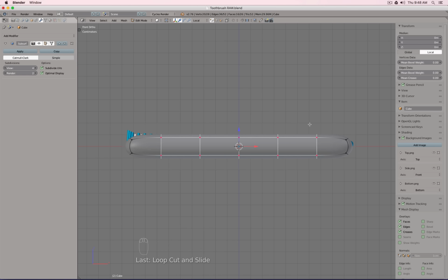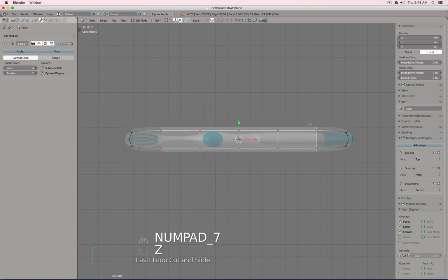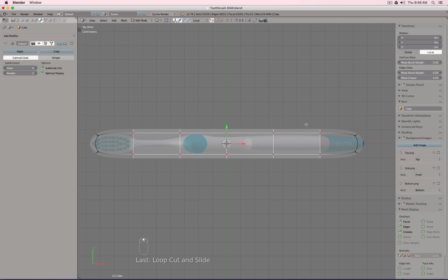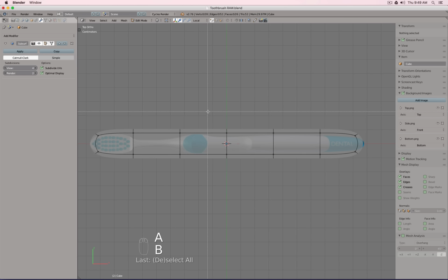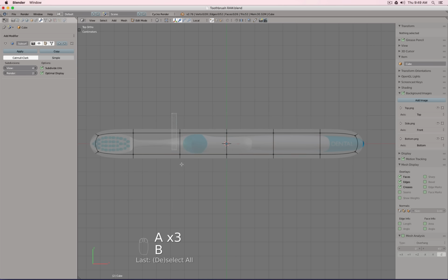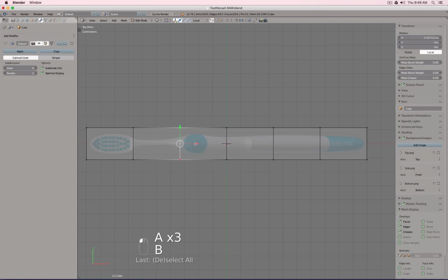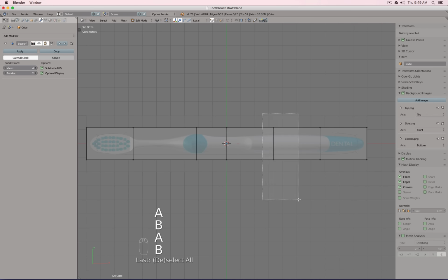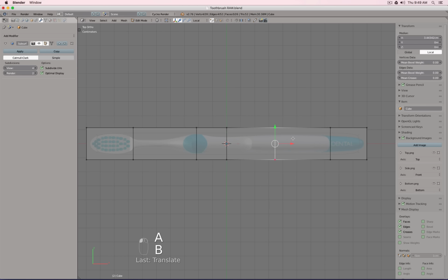So in this case now, maybe it might make sense to work from the top. So I'll try to take a look at maybe how does the curvature go. So here we have an end, here it bends out, so I need a loop cut. Here it goes down and I need a loop cut. It goes back out, I need a loop cut, and it gets down, I need a loop cut. Okay, so now let's try to rearrange those loop cuts I have for a moment. And there, this one stays, and maybe that one goes to there.